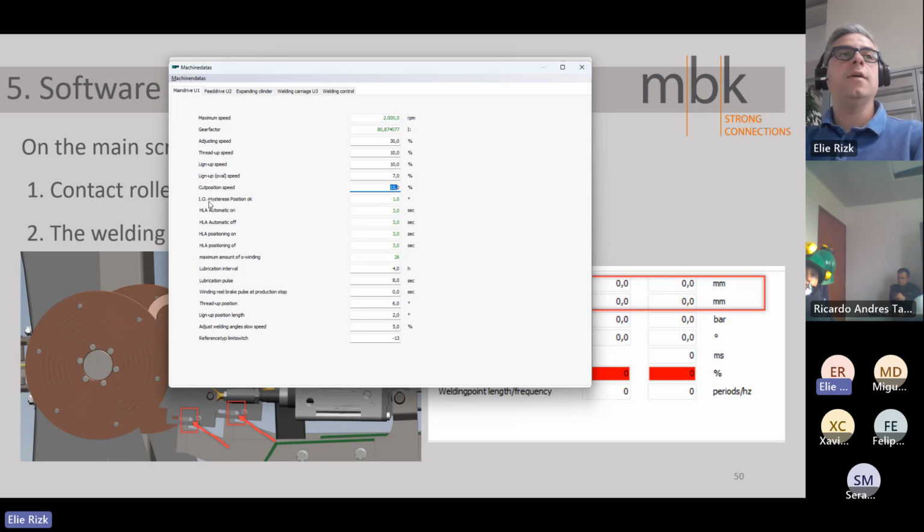So this is the position. Here we say hysteresis position. When the main wheel's nominal value should be 300 degrees, but it is 300.01, this is okay. 300.5 is also okay. When it is more than 1 degree, then it gives you an error that the main wheel is not in position. This is the tolerance for the main wheel.